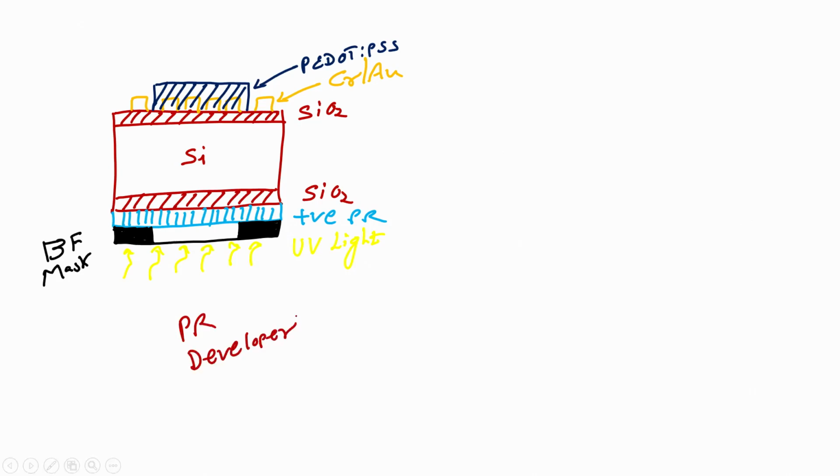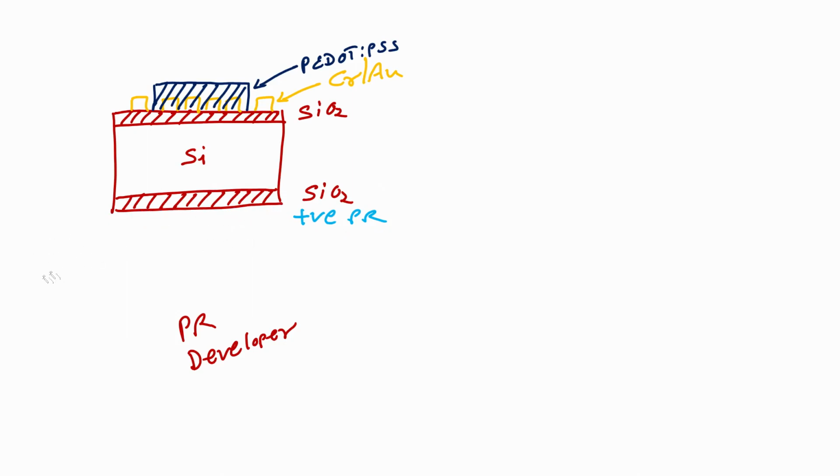If I dip the wafer in a photoresist developer, what will happen? I will have photoresist in this two area and this area is exposed now for further process. So, now what can I do? I have to go for hard bake, right, photoresist developer, then hard bake.